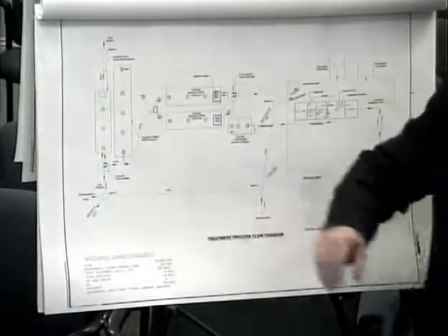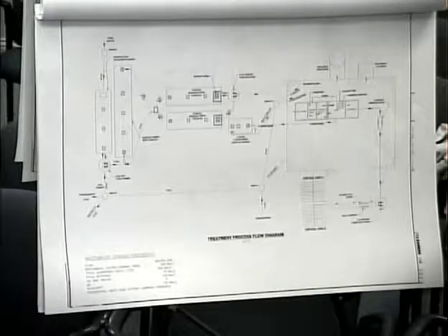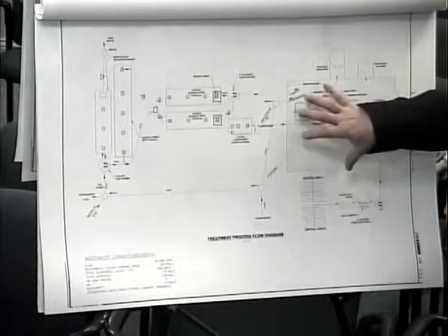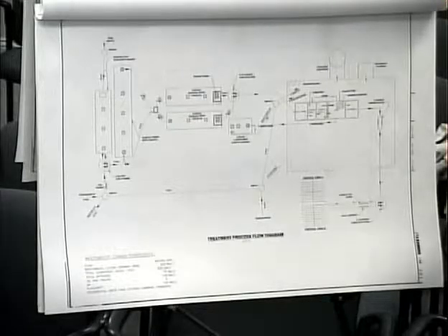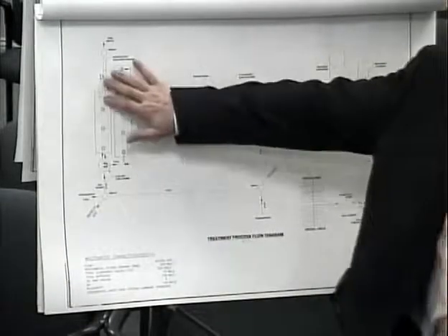The typical scenario, this is one of our past jobs, this one was around 60,000 gallons per day. The typical treatment process is basically you would bring the wastewater flow into what we call a flow equalization tank, so that any peak flows are basically dissipated. The easiest way to run a treatment facility is to have a regular flow going into the process throughout the entire day. Not to have a peak flow in the morning and a peak flow at night. Basically to try to equalize the flow so that you have the process just running continuously in one mode. So we typically put in a flow equalization tank.